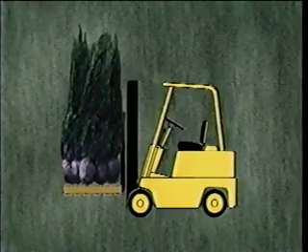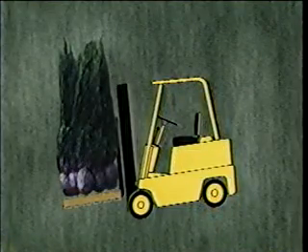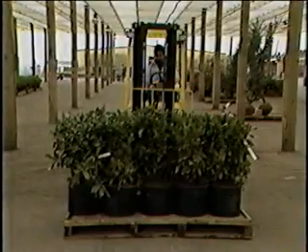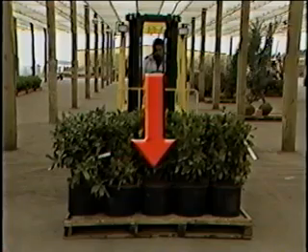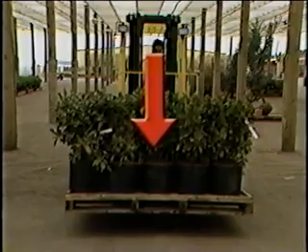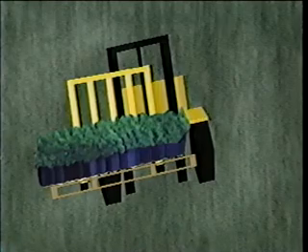If the load is above the rated capacity of the forklift, or if it is placed incorrectly on the forks, the center of gravity will be off and cause the forklift to be very unstable. The center of gravity of this load from side to side is here. Again, it is very important when carrying a load that you have the center of gravity between the front wheels. As you can see from this illustration, if the center of gravity of the load is too far off to one side, the whole forklift could tip.